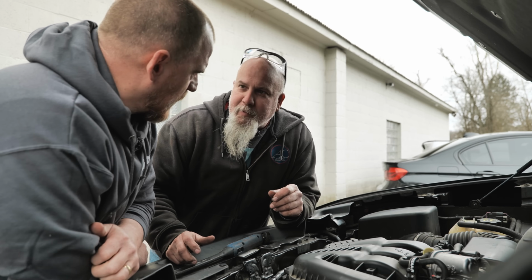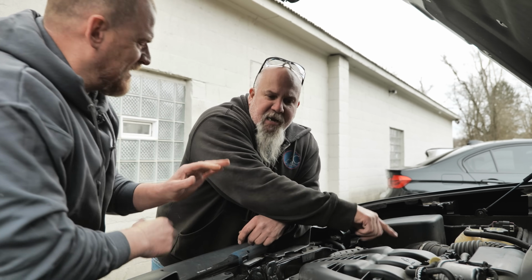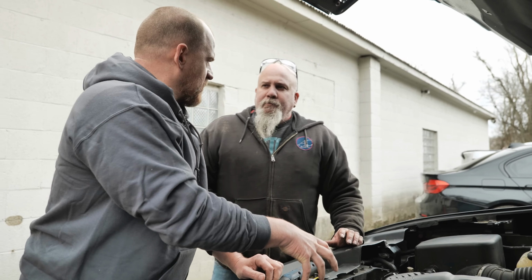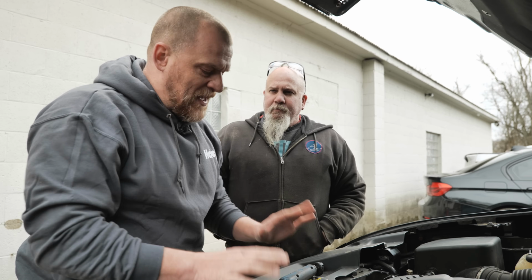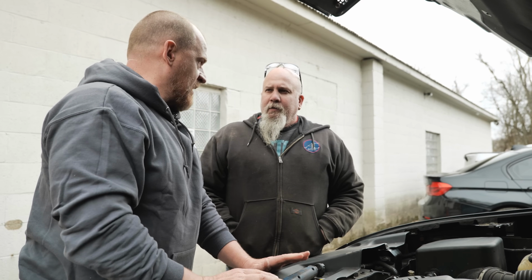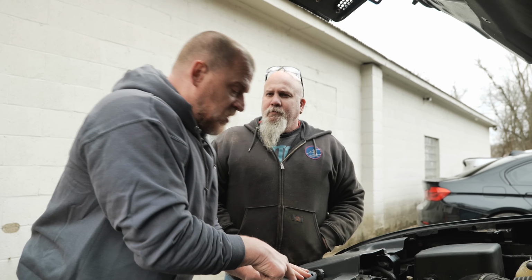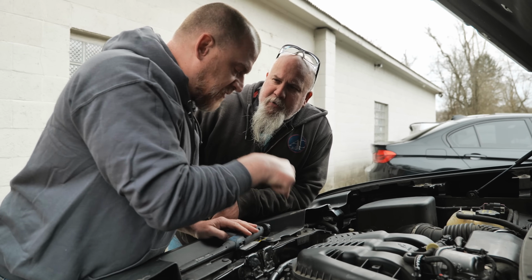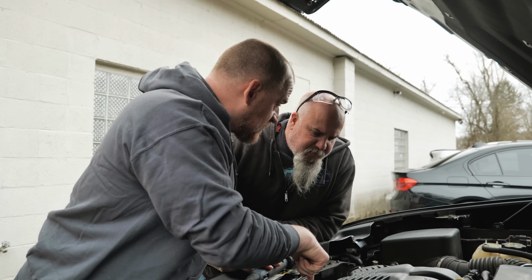Antifreeze was leaking everywhere when it was brought to me. So antifreeze was all over. Okay. So that antifreeze leak happened before this current situation. This started first, before this current situation. That makes me feel so much better about rolling the dice and putting a sensor in this, because it sits right there. You probably got antifreeze down inside of that oxygen sensor. Right, in that sensor itself.